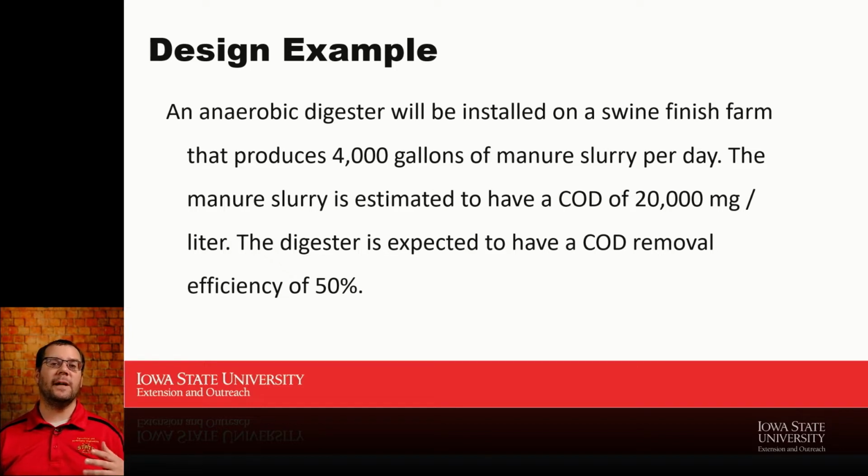When you use chemical oxygen demand, you do need an efficiency. How much of that chemical oxygen demand are we going to break down during digestion? There are some different estimates for different types of materials. For manures, I often use in the neighborhood of 50%. It works out relatively close from some design experience we have. When you switch to lignocellulosic materials, other materials where we don't have as much experience, estimating that number gets a little bit more difficult, but we do tend to have some design guidance out there.